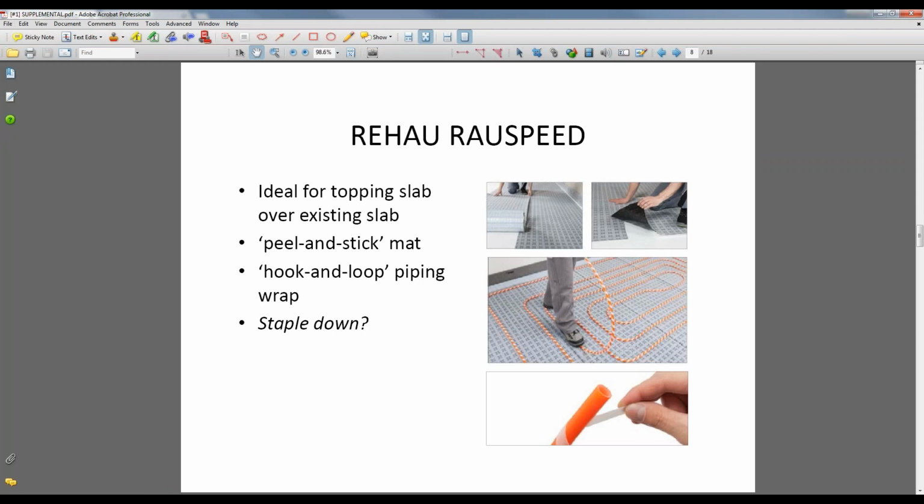Okay. One other overpour installation technique that has come out recently from Rehau, and I'm sure other manufacturers have something similar or on their way to providing something similar, is called Rehau Speed or Railfix Speed. It's an overpour type application, so it's for a wet install as we were just discussing, but it allows you to connect to a subfloor without using a fastener specifically.